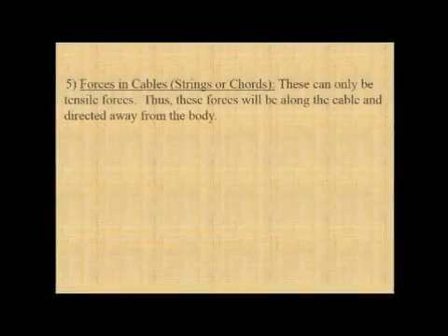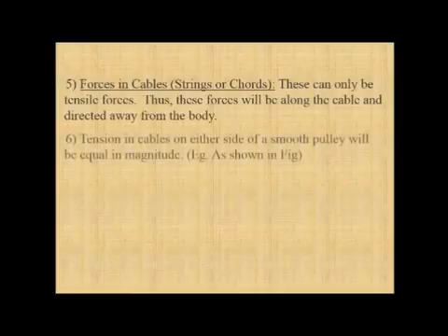The forces in cables: if you attach a string or cord like that, then there can be only tensile forces in that case. Thus these forces will be along the cable and directed away from the body always. Tensions in the cable on either side of a smooth pulley will be equal in magnitude. If you face such problems, with a pulley and two cables attached to the two sides of a smooth, frictionless pulley, then they will experience the same amount of force.